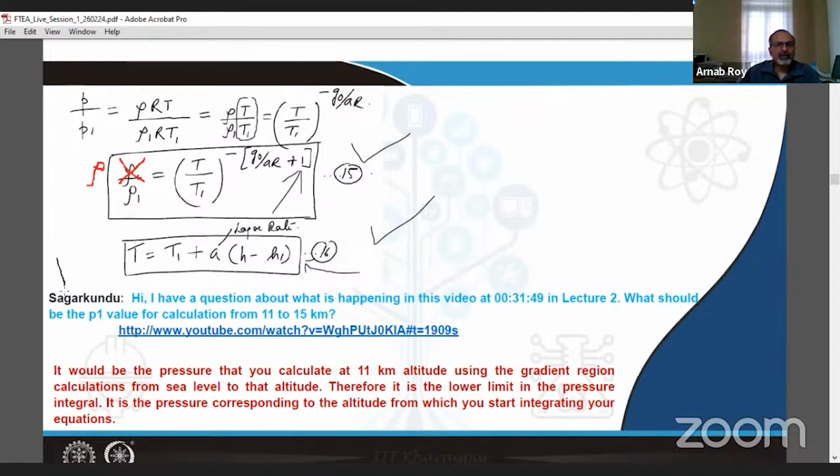And in this connection, Sagar Kundu has a question where he asks what should be the P1 value for the calculation from 11 to 15 kilometers. So this is a question related to the small problem we solved towards the end of lecture 2. The response to that is that it would be the pressure that you calculate at 11 kilometers altitude using the gradient region calculations from sea level to that altitude. Therefore, it is the lower limit in the pressure integral. It is the pressure corresponding to the altitude from which you start integrating your equations.